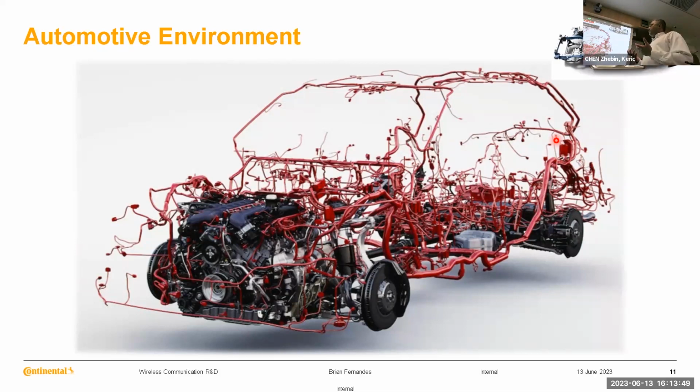And you see that typically a vehicle is not grounded to earth, so it is essentially a floating ground. What this means is that all of the ECUs in the vehicle have to be able to tolerate a certain level of voltage variation, ground variation. This also means there's going to be a lot of reflections inside the vehicle, current passing from unit to unit. All of these are part of our robustness requirements for the electrical design of the ECUs, the ability to tolerate these variations. But this also affects the RF as well. The RF module would be equally subjected to conditions like this.